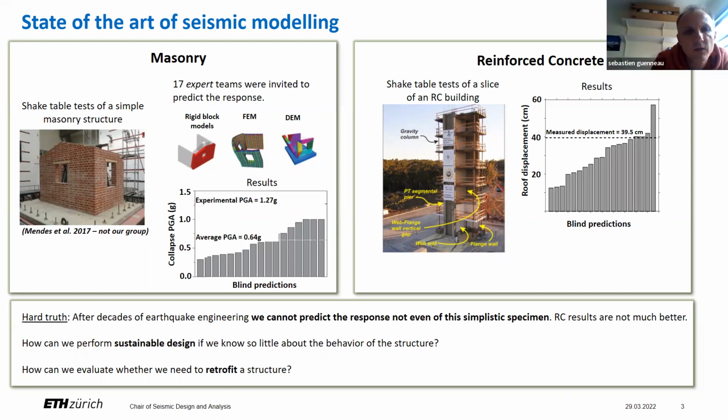And what kind of frequency for this shaking table? What is the typical frequency? So in the prototype scale, an earthquake would have dominant periods between 0.5 seconds and maybe 1 second, 1.5 seconds. If you go to a model scale of 1 to 4, these periods would be 1/2 of this.